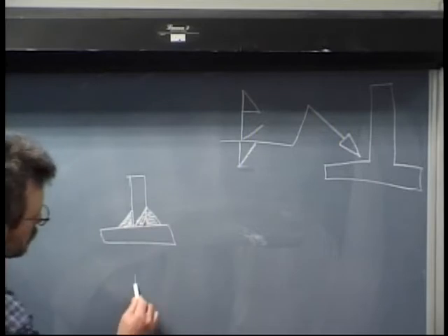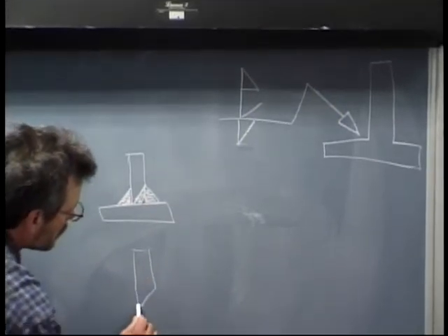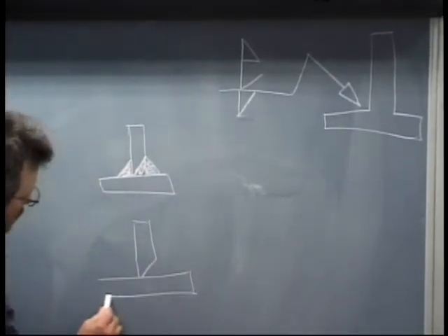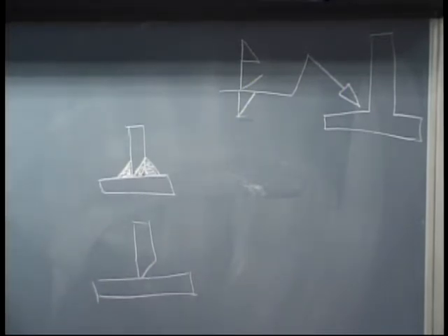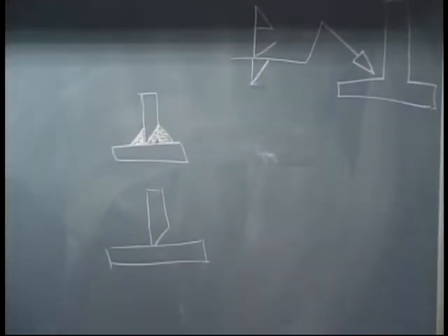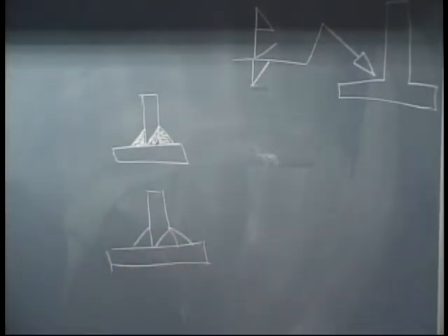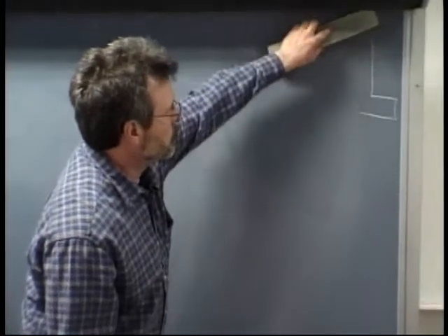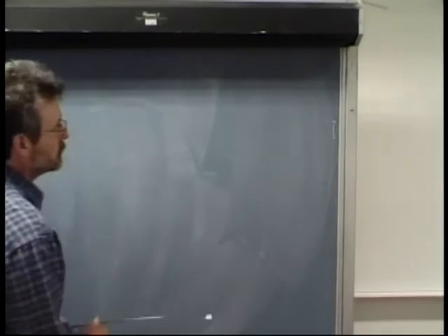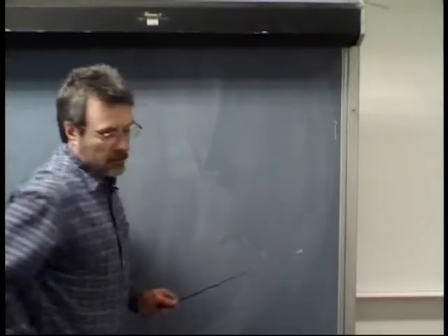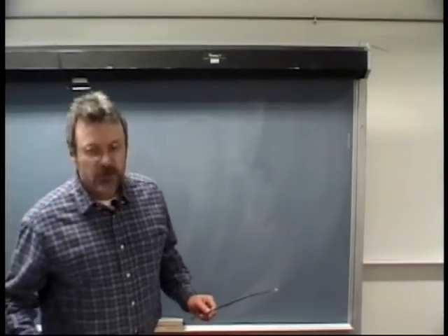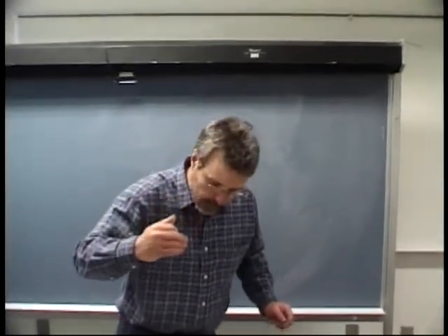Okay? So this is what the preparation would look like. That's what your two pieces of steel would look like before you began welding. Fillet weld, single bevel, fillet weld. Fillet weld, single bevel, fillet weld. And that's the way you read them. The other one's just the same, with the exception that you're doing a single J on that one. So one element at a time, start at the reference line, read out.